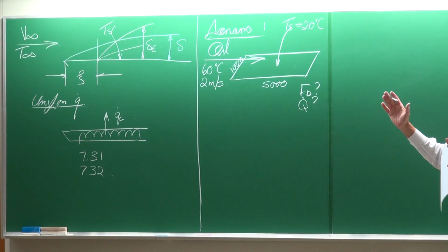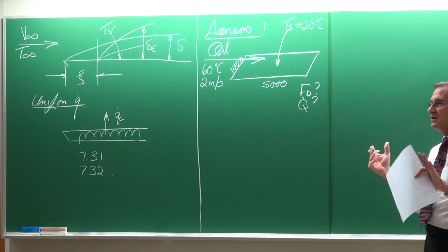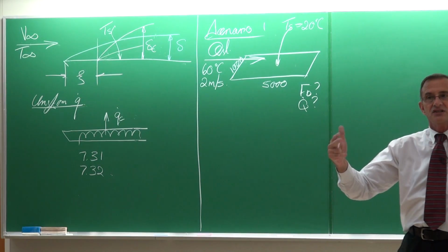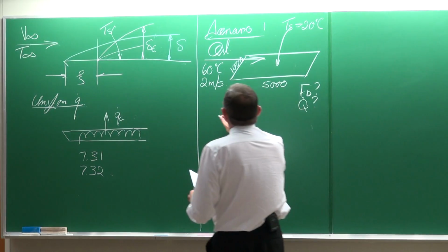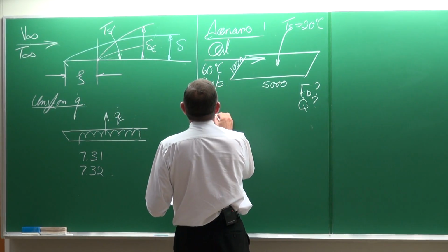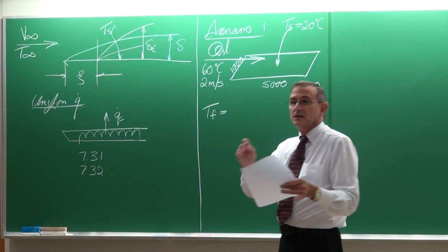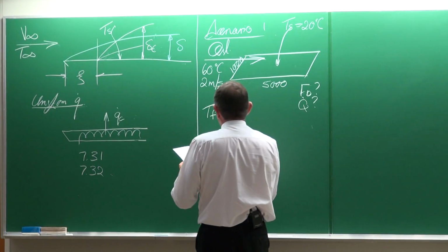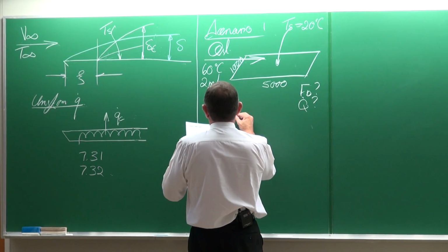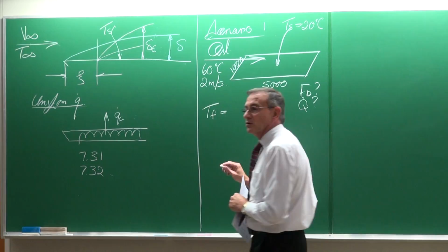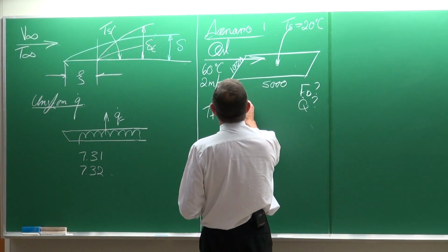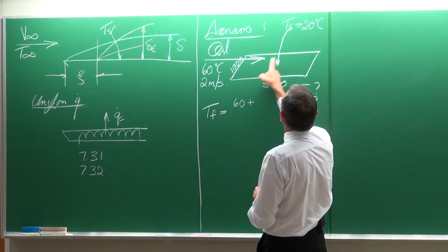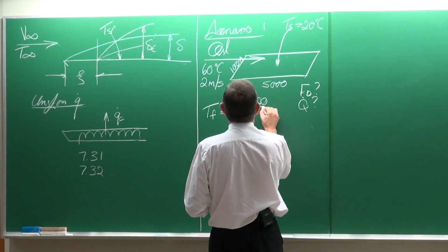With convection heat transfer, we are always interested in the properties. We need densities, viscosities, Prandtl numbers, etc. So, where do we get it? Well, we first get it in the tables in your textbook in table A-13. But we need to go and look at what temperature we should do it, and for that we use the film temperature, which would be that temperature plus that temperature divided by 2.